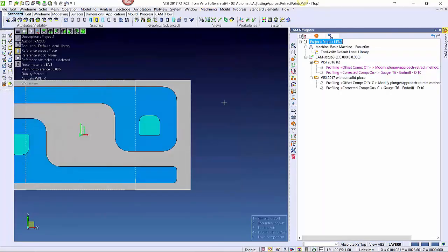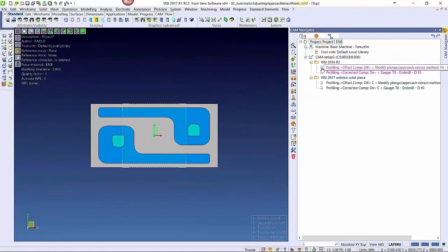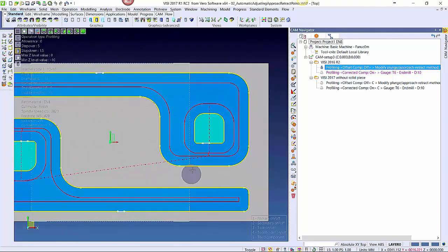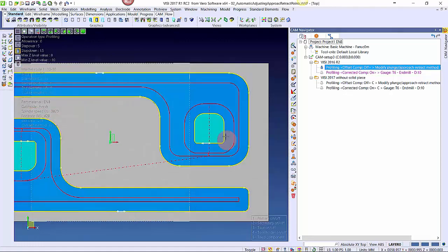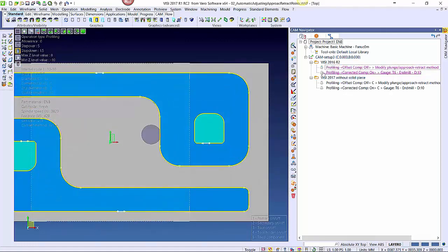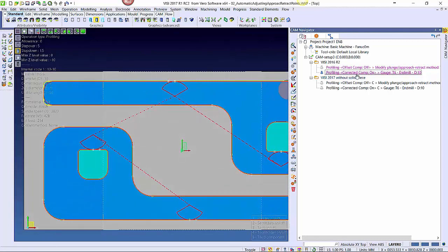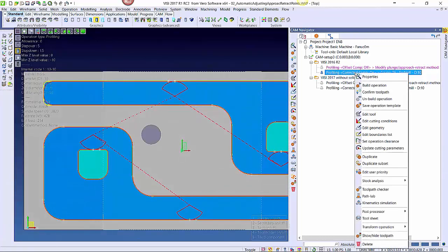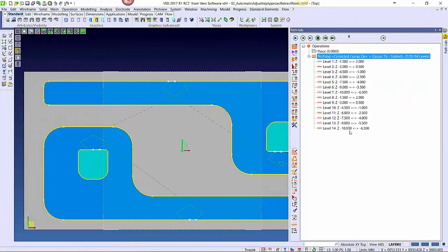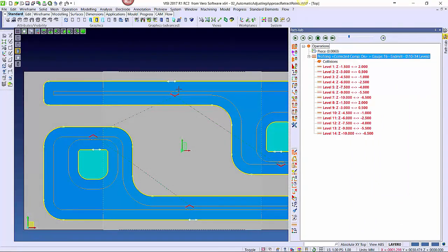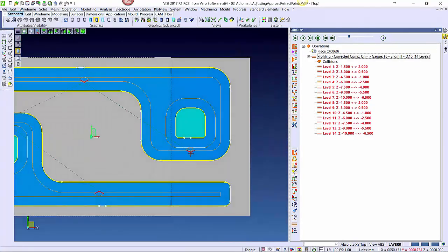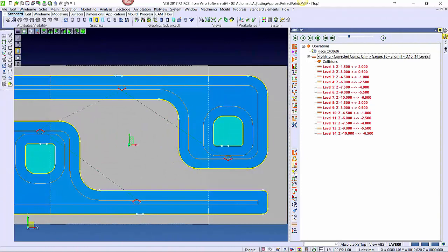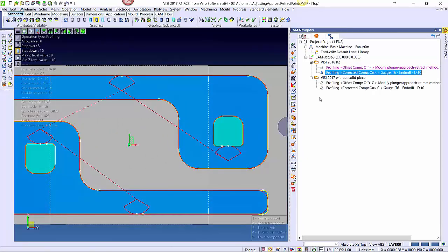as the rest area. So in here, you can see the not aligned status. You can see this is the old toolpath from the milling. When we right click here, you'll also see the confirm. See the confirm toolpath, you can actually select that. So let's take a look at the 4 diameter comp. And you can see when it's actually leading in this area for the diameter comp, it's actually colliding. See the red.